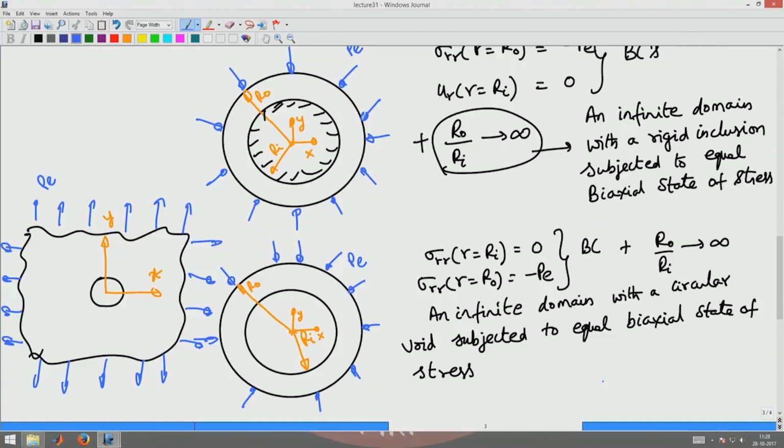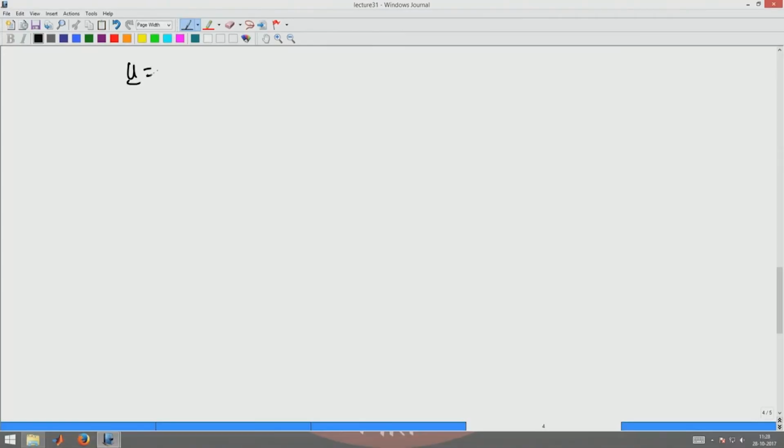Okay. So, in all this we had the basic displacement field as u of r times E r, but this also can change. I can superpose axial deformations which will be plus epsilon z times z E z, which is the axial expansion or contraction; the axial displacement is given by epsilon z times z.